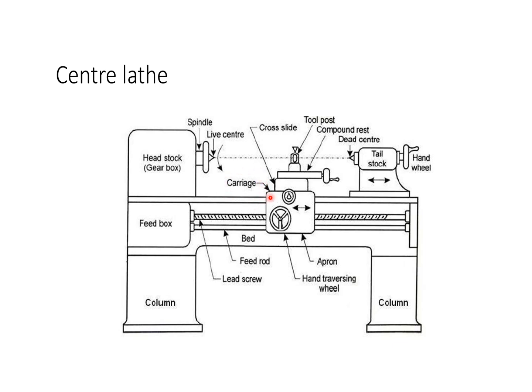Next, carriage. The carriage is supported on the lathe bed base and can move in a direction parallel to the lathe axis. The carriage is used for giving various movements to the tool by hand and by power. It carries saddle, cross slide, compound rest, tool post, and apron.